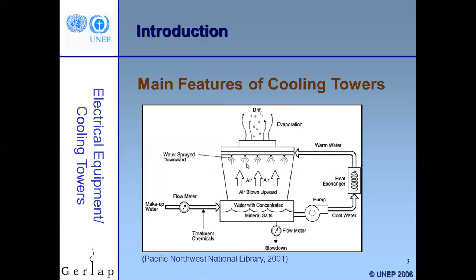We'll talk about that. We get some evaporation, which causes the cooling of the water stream as it goes through here. A little bit of straight convection, but most of the cooling is by evaporation. It's possible to throw droplets, that's called drift and windage, out of the tower. We have some mist eliminators on the path to try to keep this down to a minimum. And then, of course, the water falls back down, having been cooled, into the basin.